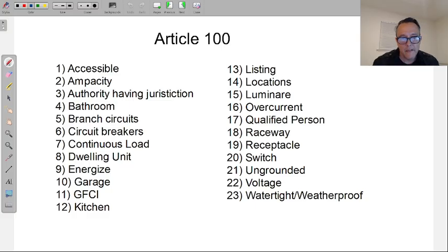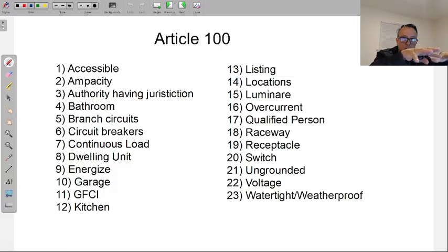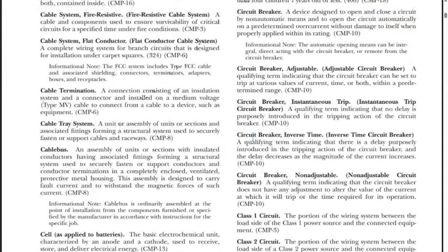It will trip instantly. So this is good for like a main breaker, like the main breaker that's at the panel. And then you have all of your little individual branch circuit breakers. Your branch circuit breakers delay, inverse time. Your main breaker, that's the one you want to have as an instantaneous. All right, just to give you a example of one of those.